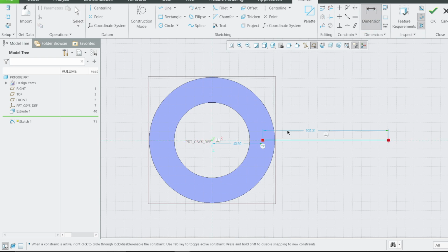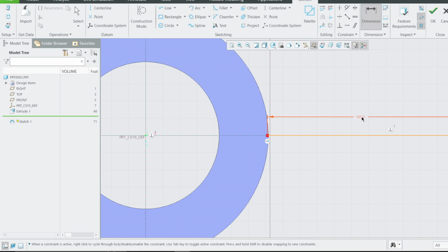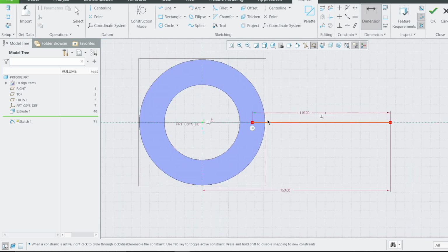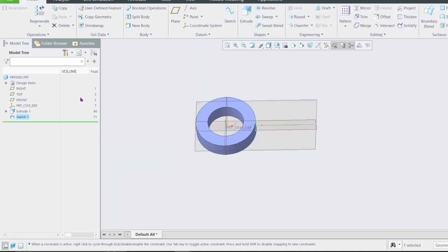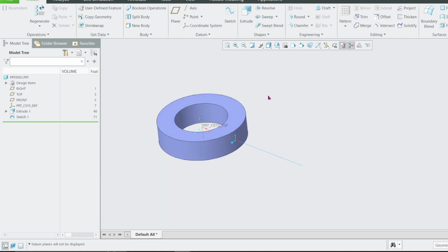And I want to define my blade length as maybe 150, and I want this length here to interfere with this surface a little bit, so that once I merge, I'll be sure that the surface here and this are interfering for them to merge to each other properly. You can give it a name there. Then we select this one here and say sweep.